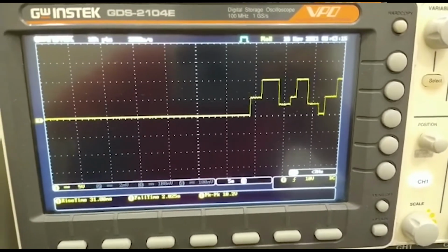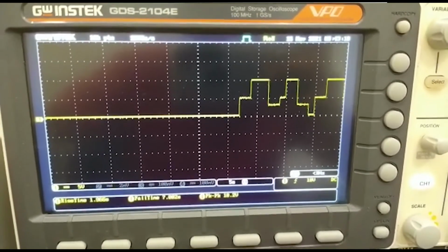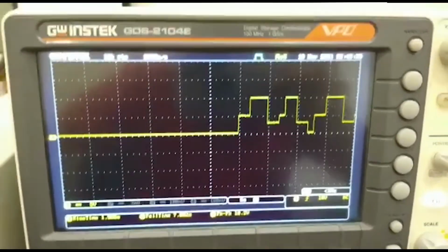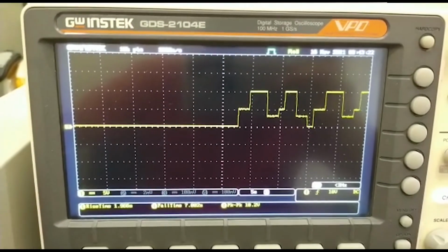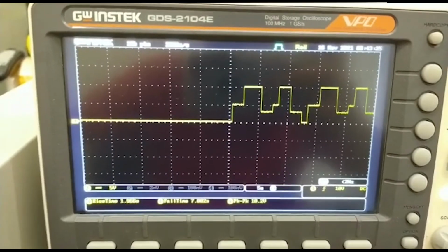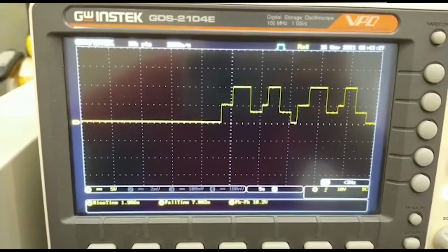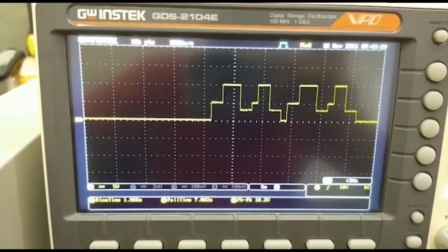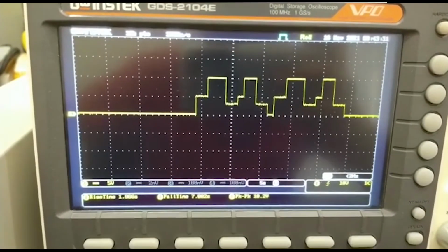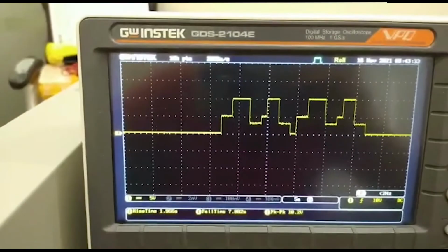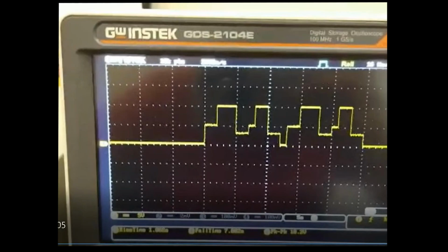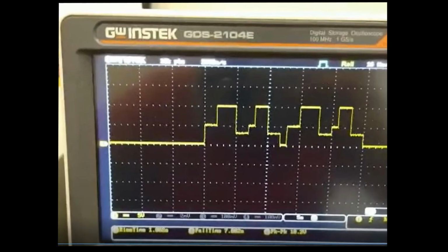So something like this on a more expensive program would probably cost a good amount of money. So we're trying to give the customers a little bit more bang for the buck when we offer this type of test script function, which makes your patterns a little bit easier to program. Yes, it may seem difficult at first, but once you get the hang of it, it should be pretty easy. Kind of is. It's pretty much just program it into your Excel file, upload it to the USB, and just upload it to the power supply, and voila, you have a sequence of this nature.